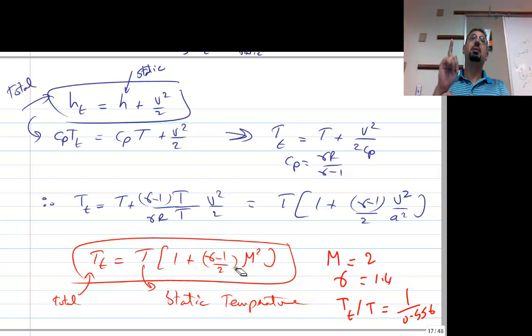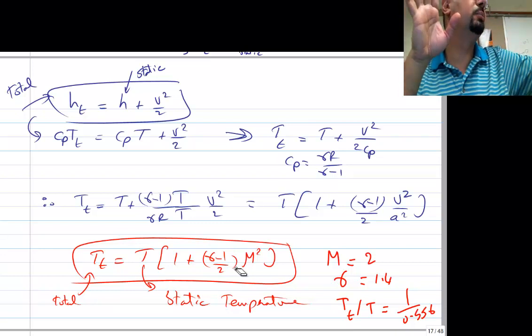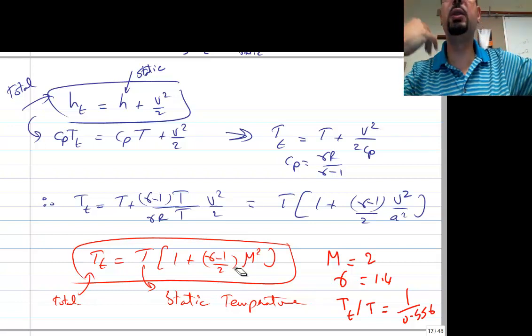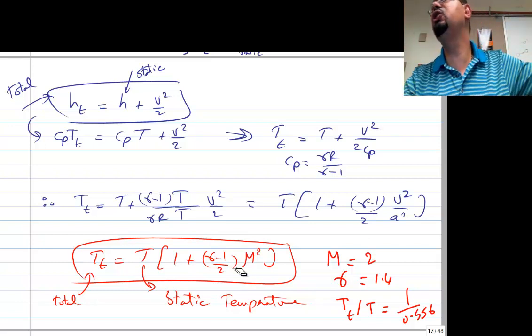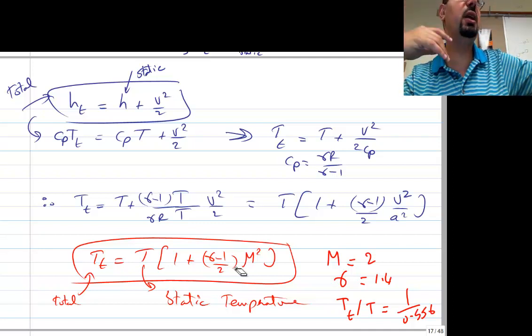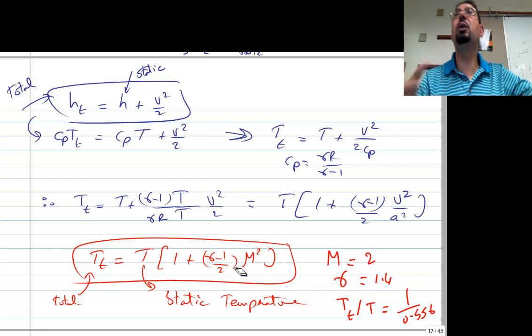In the quizzes and the exams, don't interpolate in those tables, to go faster. That's the point of using the table. So when I tell you a Mach number, what's the jump in the table? 0.02. So you just pick the closest 0.02. So if I say 0.03, you are free to pick 0.02 or 0.04. So don't interpolate in the table.